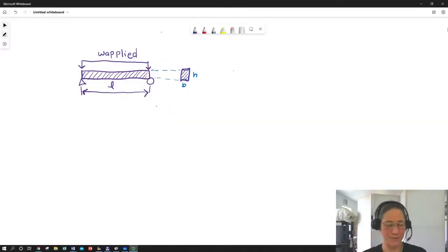In this lecture, I'm going to go over the basics of sort of a free-form beam design. The things that we're going to consider for this beam are longitudinal stress due to a flexural type applied load. We're not going to include any kind of actual axial compressive or tensile loads. We're going to also include deflection, so we don't want the beam in the middle to sag too much or the ends to go up too much. And we're also going to consider shear, maximum shear. So we're going to look at longitudinal stress, deflection, and shear.